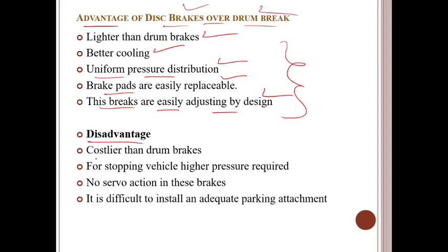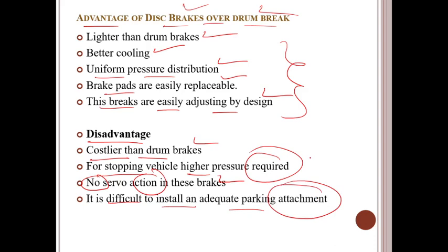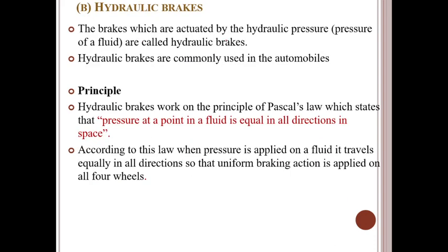What are the disadvantages? Costlier than drum brakes. For stopping the vehicle, higher pressure is required. No servo action in these brakes. It is difficult to install and to provide adequate parking attachments. So these are the various disadvantages of disc brakes.